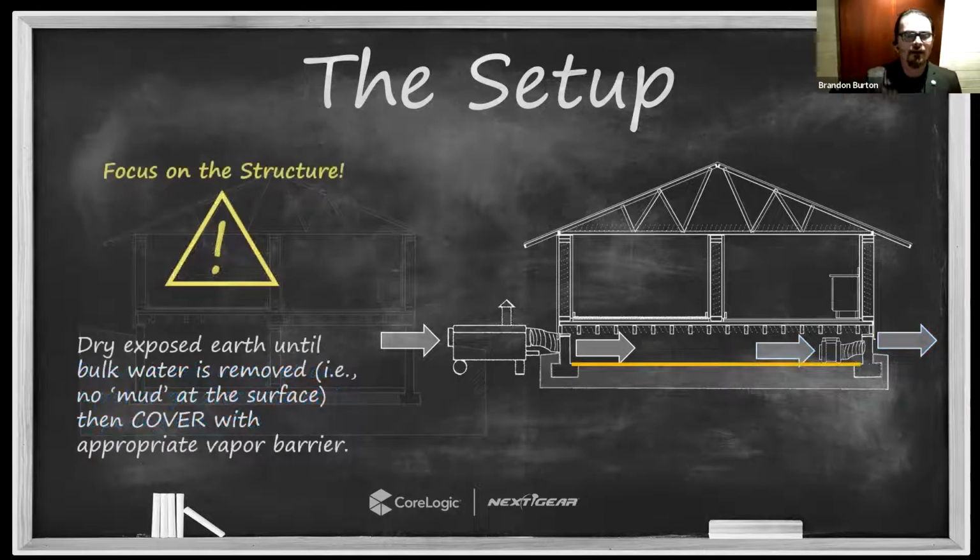All right. Here's the next note I want to give you on dealing with crawl spaces that I think often gets misunderstood and overlooked. The purpose in drying a crawl space is to dry the structure. It's not to dry the dirt. And I'm going to say that a couple of times because I know this is one where some of us could probably argue back and forth in a couple of different directions. But the purpose of drying a substructure is to dry the structure, not to dry the dirt.